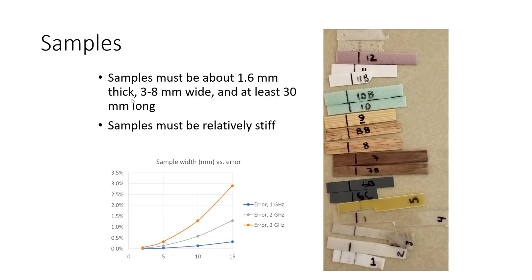A little information about the samples. You want to make them at least 30 millimeters long. You want to make them 3 to 8 millimeters wide. And I find that being closer to the 8 is going to give you a more robust result.